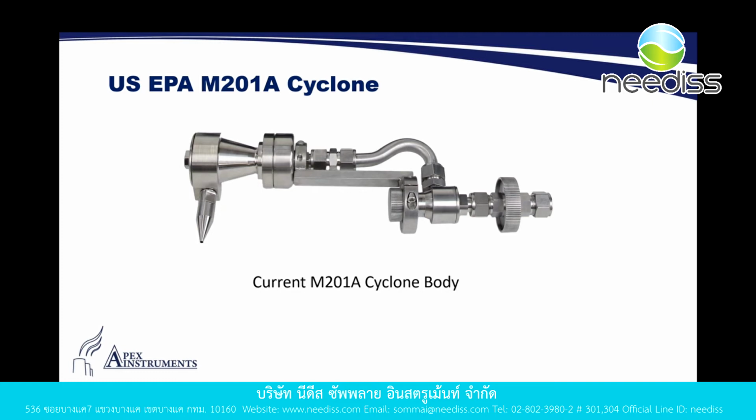Just to make reference for everybody, if you're doing the combination of PM10 and 2.5 together, you must allow yourself a 4-inch port opening on the stack. Typically 4 inches is enough for this particular one. We have one other design that needs 6 inches, but this one would be 4 inches. And I mention that because for Method 5, you really only need a 2-inch opening. But because of this size, we do need 4.